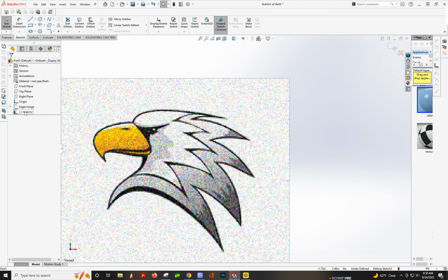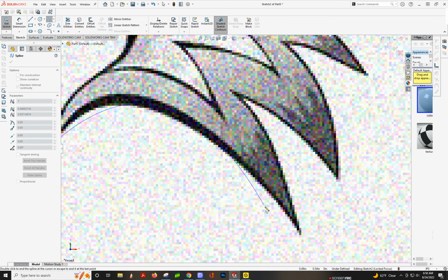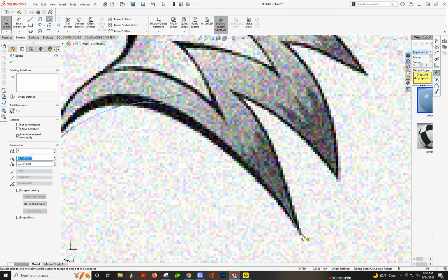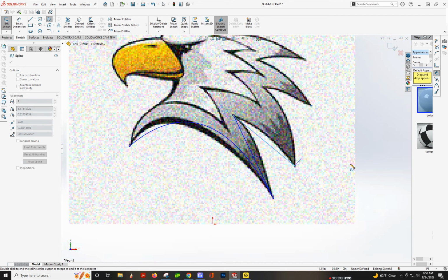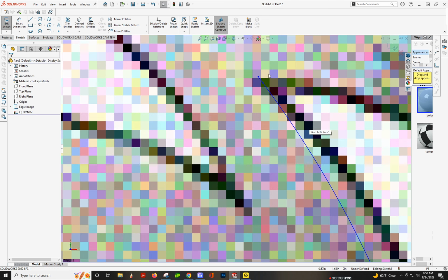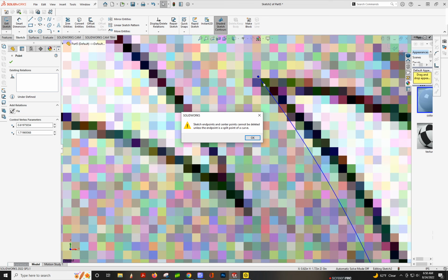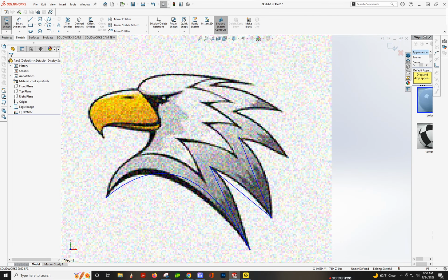Okay, so on our new sketch, we are going to do peaks and valleys. So click, click for the curve, double click, a quick double click. If you don't do the double clicks quick enough, you'll have a little tail, and that is bad. So I'll do that. Here's the tail. So you can't delete the endpoint. You have to delete this anchor point. So that's the only thing with the double click.